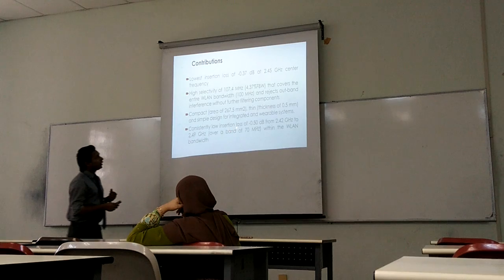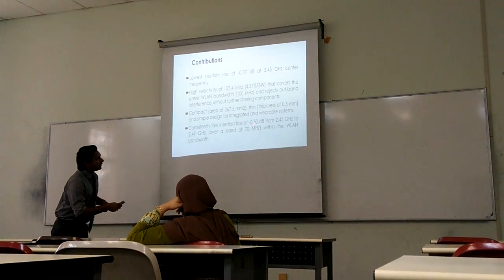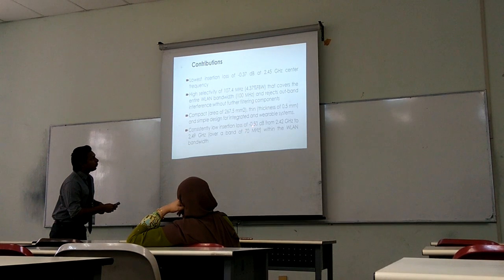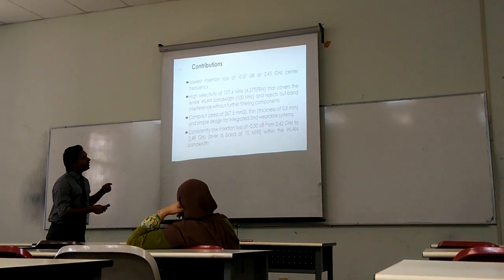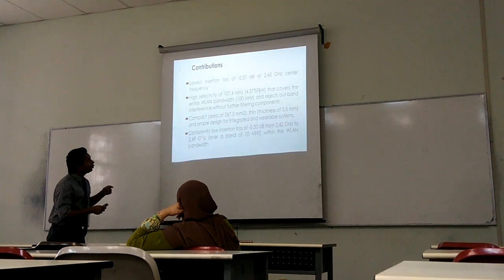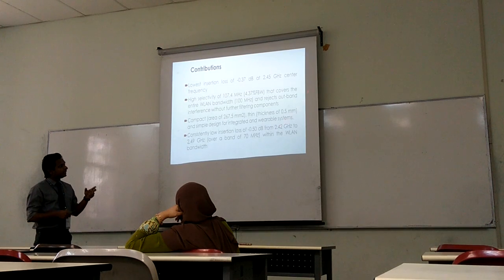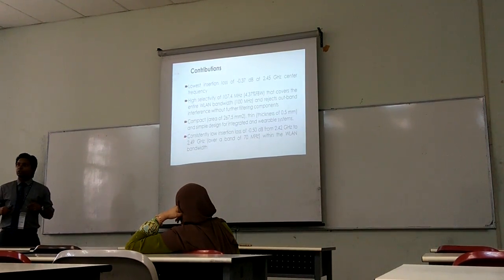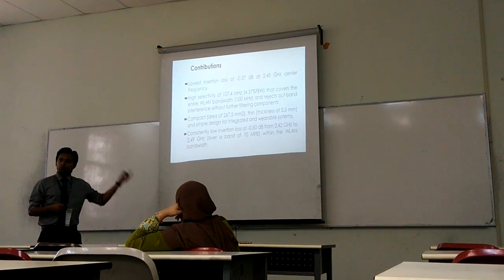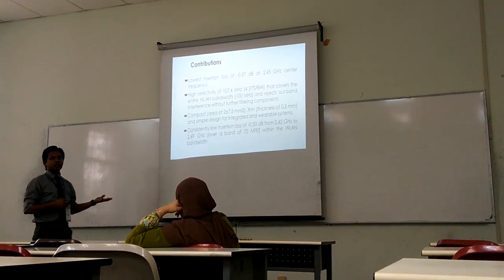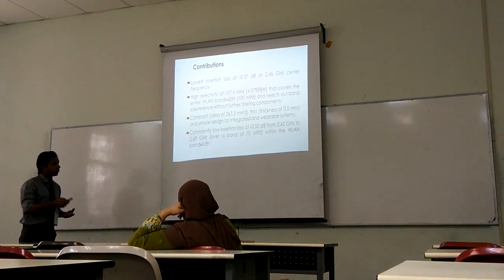And the consistently low insertion loss that we have shown in the results section. The insertion loss level is lower than minus 0.5 dB from 2.4 to 2.49 GHz, which means 70 MHz within this band of 100 MHz. So this is the major thing that we can claim is interesting, because we have found it from the simulated response. So these are the major contributions of this work.